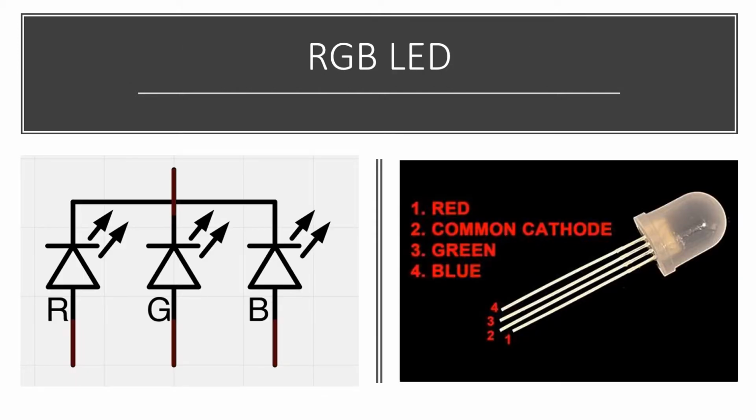All right, this is the RGB LED. So in other words, red, green, blue light emitting diode. It can flash either red, green, or blue, or some combination of them. This is essentially what we have in our LED screens on our computers. And you just generate the color you want by sending current through 1 for red, 3 for green, 4 for blue, and the power comes back out the other end through our common cathode. That's the longer of the leads, lead number 2.